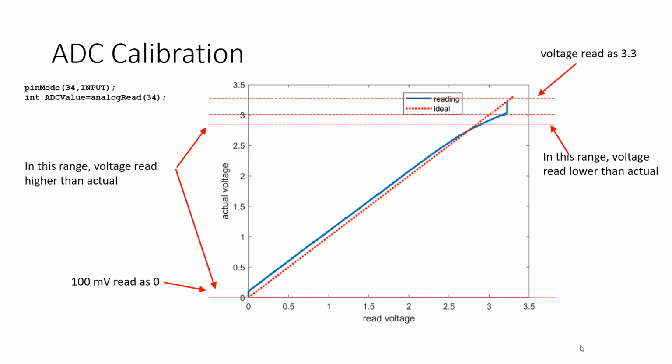So the idea is basically to auto-calibrate. There's two parts to this lab. The first part is you're going to use UART to connect to the power supply and talk to it, but we're not going to bit bang the UART. We're going to cheat and just use the built-in hardware UART, which in the Arduino IDE is like one line of code to set it up, and then you just print to that UART, right? You guys with me?